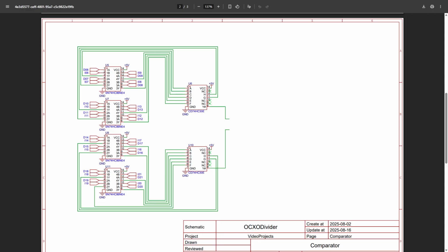Only when all the outputs of the XOR are 1, the NAND gate will output a 0. In the rest of cases, it will output a 1. To put it in words, when the numbers match, the XORs should all output 1, so that the NAND outputs 1. This is a little counterintuitive because the XOR outputs a 0 when the bits match, and not 1, which is what we want.